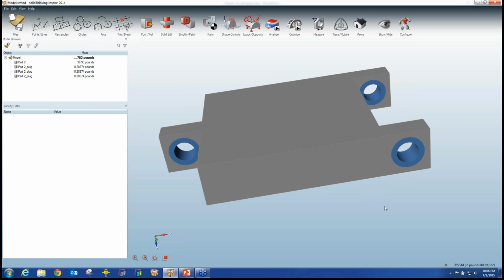The other concept with optimization is you really need to separate your design space from spaces where you apply your loads. So components where you really apply your loads are always separated from the component that you actually optimize and remove material from.